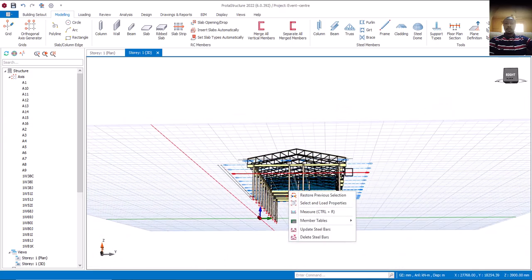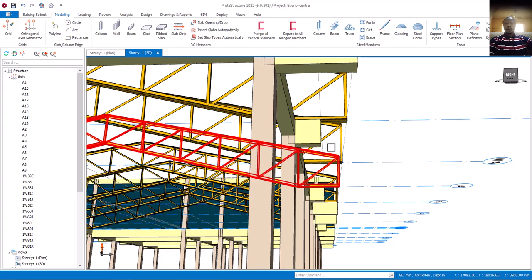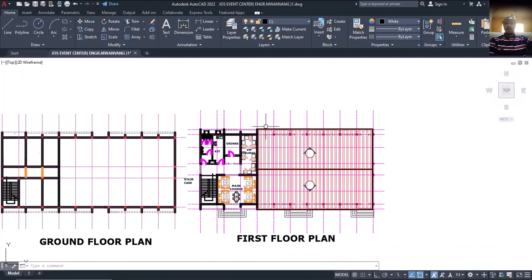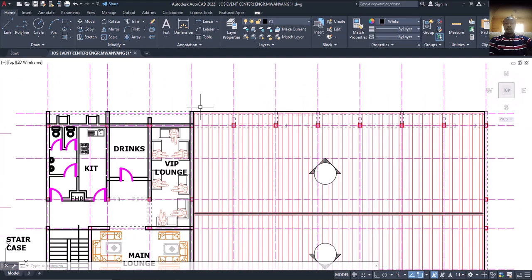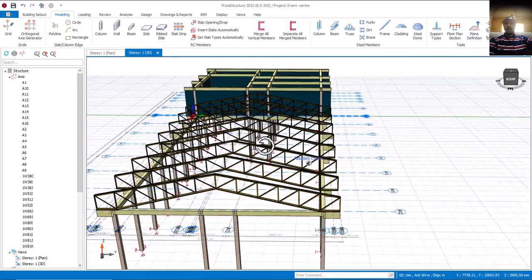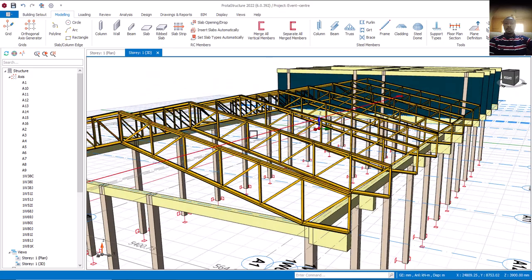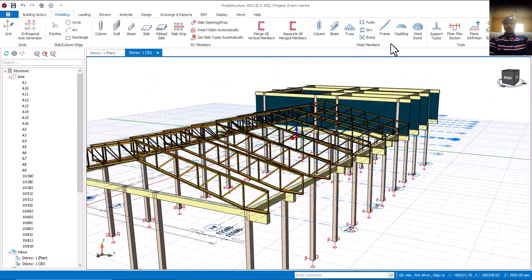You can now see that extension here, just like what we have here in AutoCAD. Can you see the roof around here? This is where our columns are, but look at where the roof member is. Can you see it now along this place? So that is fine. Now the next thing we are going to do is to put our Purlins. Is that okay? So that is that. So to put your Purlin now, I'll come to this place.